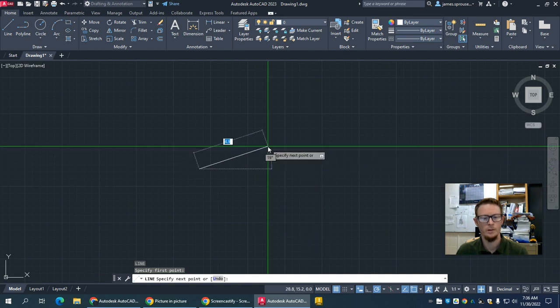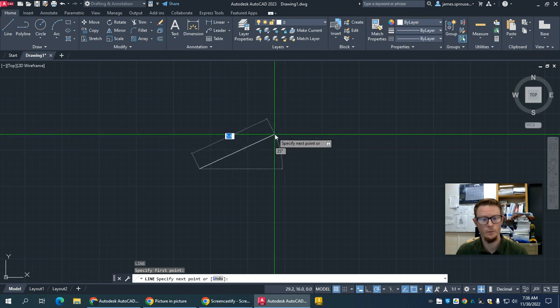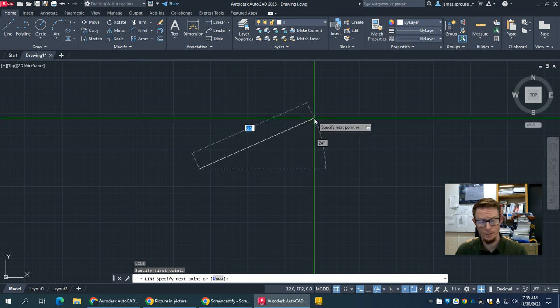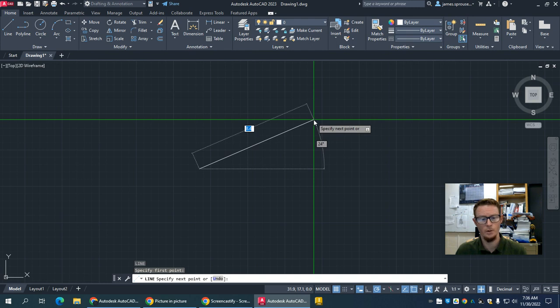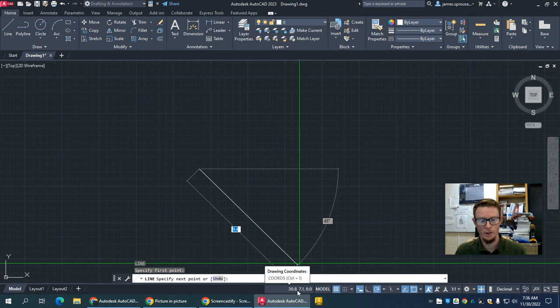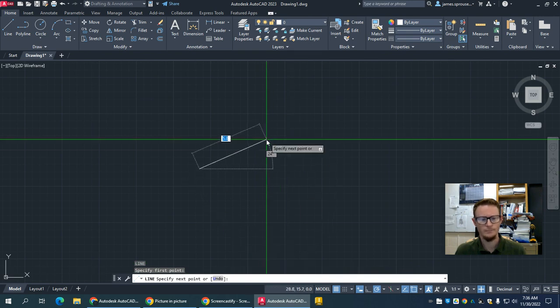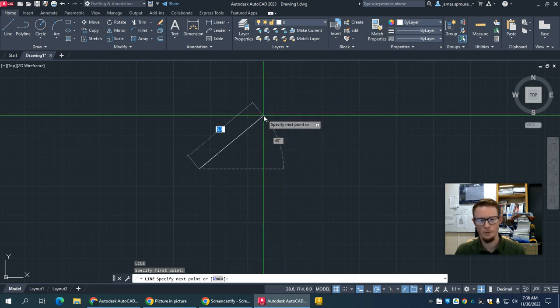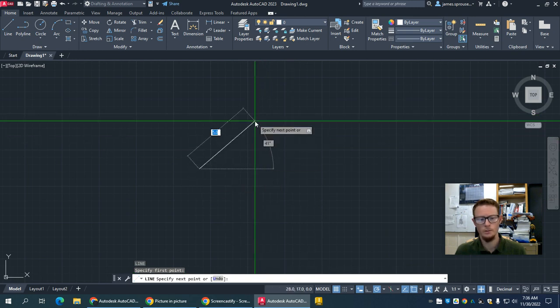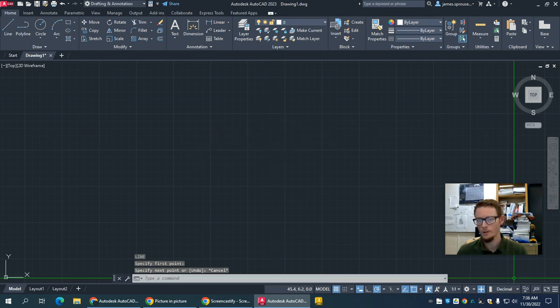And the numbers that show up near my cursor and line, the one showing the length there as it gets longer, how many decimal points are shown, that changed because of what I put in. Down here, it changed because we changed the precision. They're much smaller numbers if you've got this turned on. The degrees are just whole numbers, so that will change how this all looks. And when you start dimensioning things, it can affect that as well. So I'm going to hit escape.